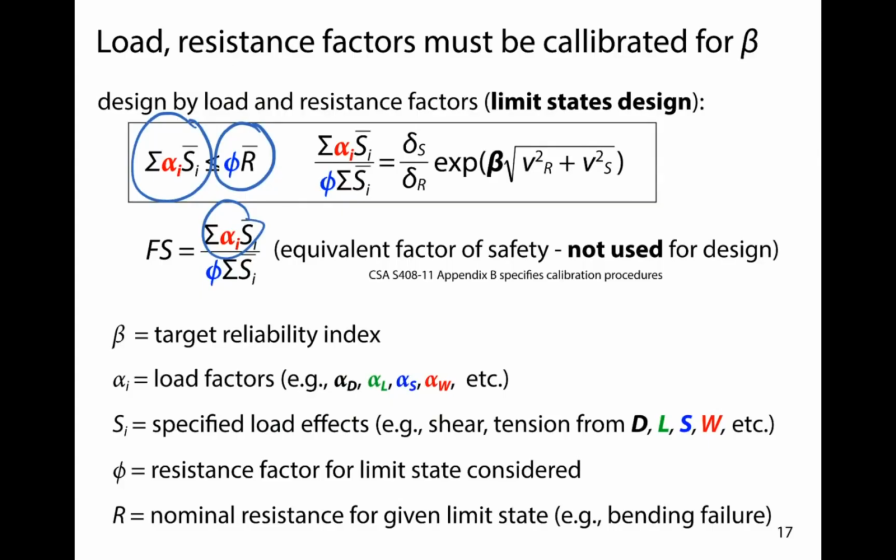On the quiz, I think I asked you to figure out what the factor of safety might be if you're trying to design something from scratch for a certain value of beta. And so basically, you should see here that factor of safety being equal to this makes these two expressions more or less equivalent. Okay. Here we're going to have different load factors for dead, live, snow, and wind load.